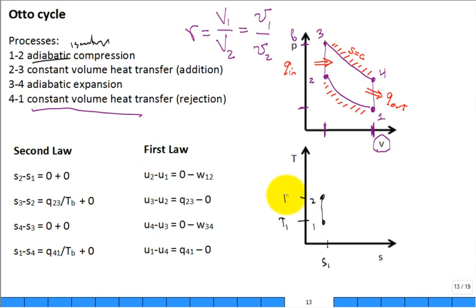You're at a higher temperature at T2. And then you have constant volume heat addition. This is probably the hardest to sketch. On the TS diagram, it just goes up at a slope, volume equal to constant, until you get up to state 3. Then isentropic expansion down to 4, and then volume equal to constant, heat rejection at 4 to 1.